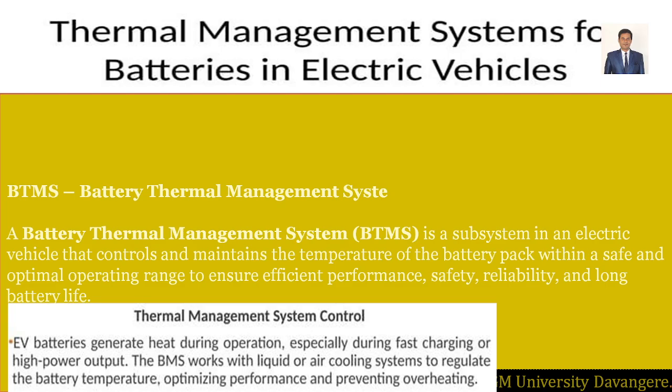Right? So, you have to turn on the PTC heaters so that the temperature will start rising in the battery. It will come to the actual temperature, right? That is the battery heater you have to use, right? Especially in most of the vehicles, like Nexon and other PVs, these techniques are included. All right. So that is one example given to help understand. All right. So BMS also plays an important role to safeguard the batteries, so that they will not catch fire.